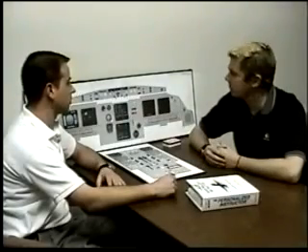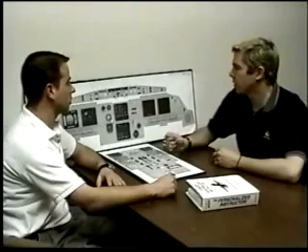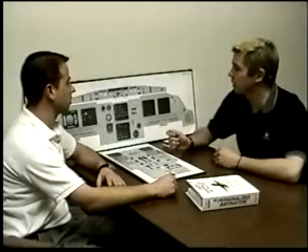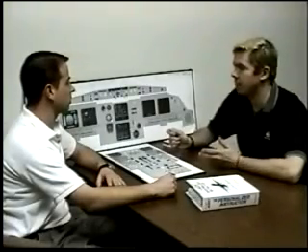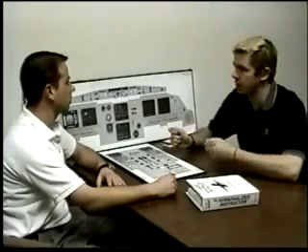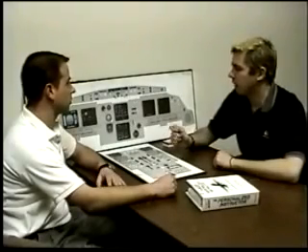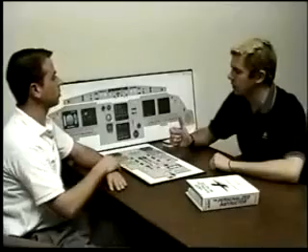It automatically clears that ECAM. If I click and hold that button for a short period of time, I'm going to hear the word, and in my case, as a first officer, I'm going to hear "priority right." And what that means is that the captain's stick is now deactivated. It can no longer make inputs. If I let go of it at this point, then the captain's stick becomes reactive, and it's the same summation that typically goes on.